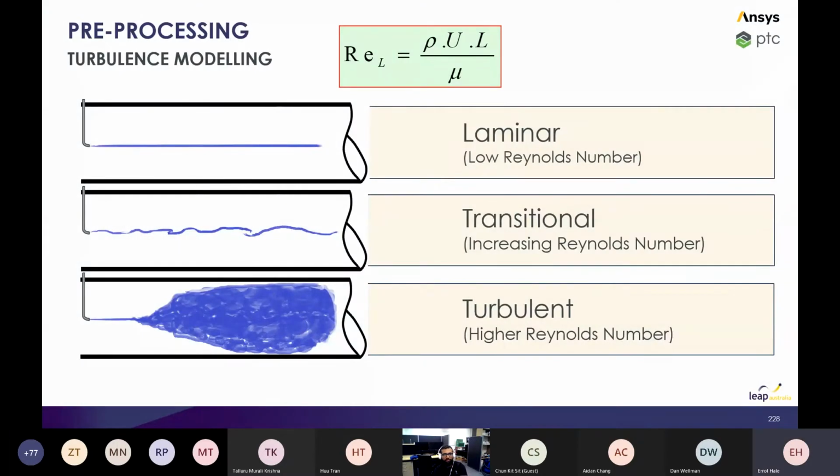So what is turbulence? Turbulence is a chaotic flow phenomenon. And really, one key point is all flow is turbulent. No flow is purely laminar, even flows that really seem laminar. At some level, there is some disturbance in the flow field. It's not a perfect free stream, everything in a straight line velocity, but there are situations in which we can model things as laminar flow, and situations in which we need to really account for turbulence.